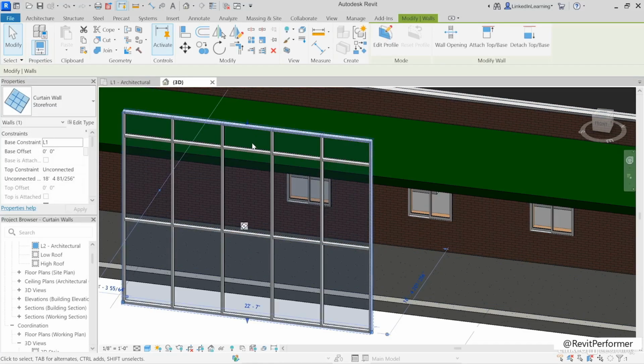And at some point, it will be tall enough that we can add a new tall bay. So what the curtain wall will do is it will add in another tall bay of the same size as the one at the bottom, and then the leftover just gets applied to the top. So it's similar to what we saw running laterally, but not exactly the same. Because in the vertical direction, we're repeating a fixed distance, but in the horizontal direction, we're keeping the bays equally spaced.